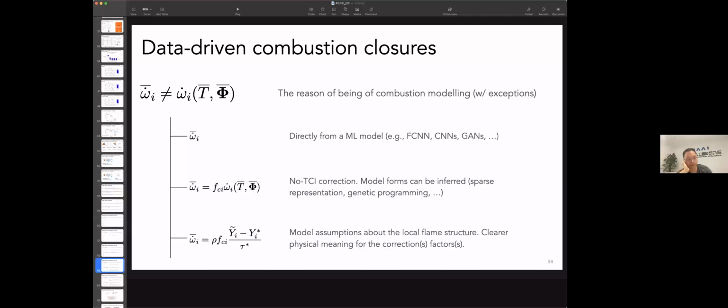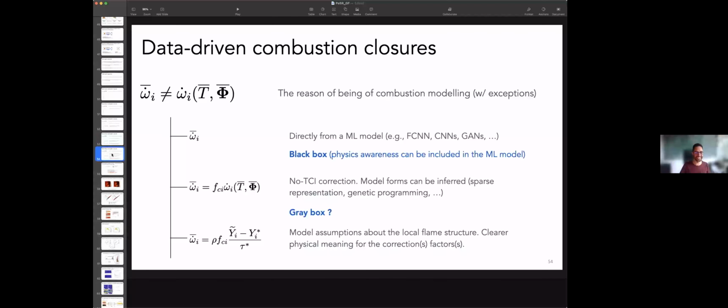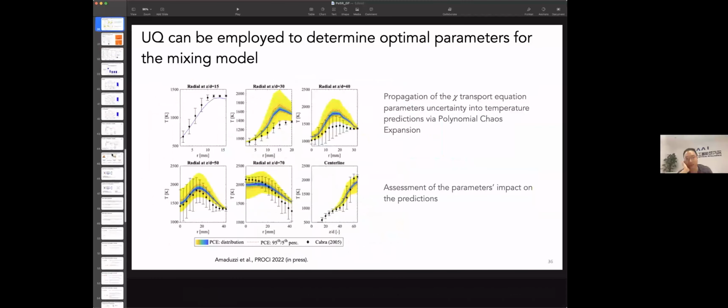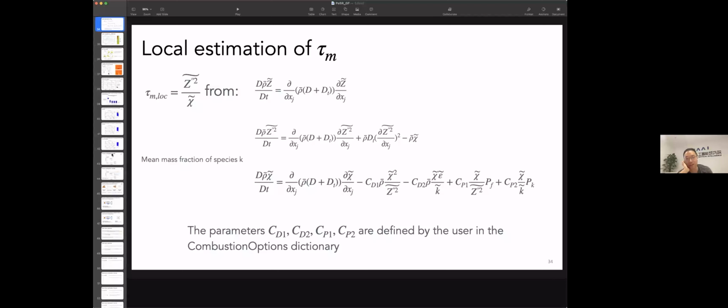Yeah. Okay. I have another small question regarding your transport equation for the scalar dissipation rate. I didn't know you were solving that. What was the reason for not using an algebraic model? Algebraic, yes. Actually, I think we tried that, but behind the algebraic model, correct me if I'm wrong, there is also a strong hypothesis on how this dissipation takes place, right? And so we basically land in a condition which is very similar to assuming a global CMix.